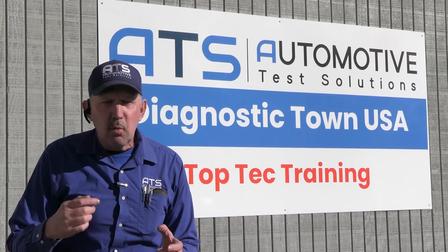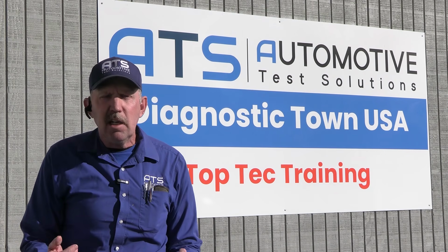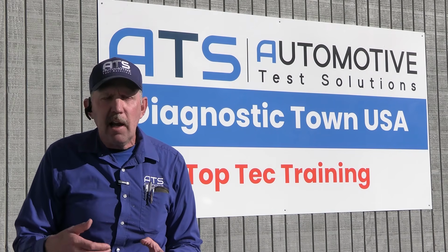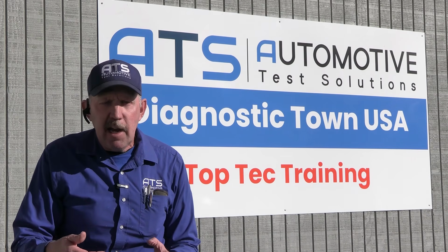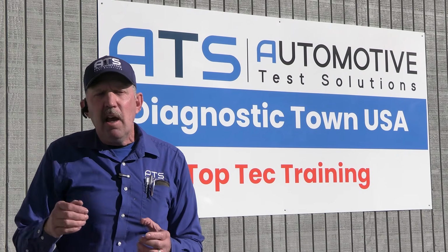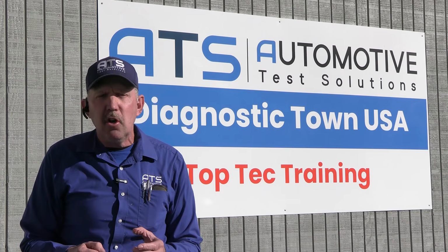And there's lots of really hard cars that I fix that the only way I can see to fix these cars is the way I'm demonstrating in these videos. With having a scope and having the understanding of how to use it and have a process to look over the data and understand the data and then let that make your diagnostic decisions. Okay guys, if you have good tools and good techniques, you too will have good troubleshooting in your base.